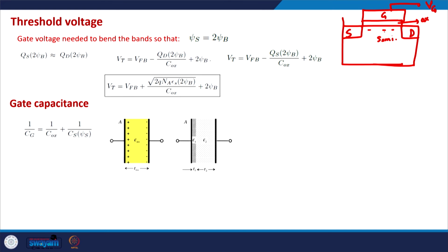So, which means that this semiconductor also has some capacitance in it, because whenever the charge is a function of the voltage, it shows a capacitive behavior. In that case, as seen from the gate terminal, we will see the oxide capacitance and the semiconductor capacitance. So these are the two capacitive elements, I would say.